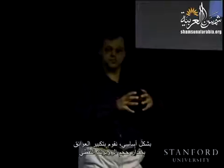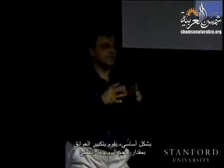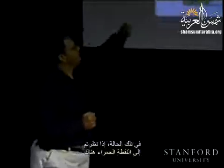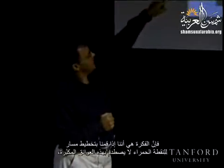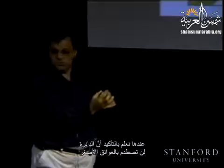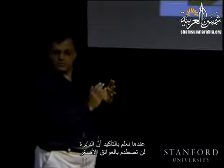Basically, we take the obstacles and we grow them with the size of the point robot, if you want. If you look at the red dot there, the idea is that if we plan a path for the red dot that doesn't collide with these grown obstacles, then we know for sure that the circle is not going to collide with the smaller original obstacles.